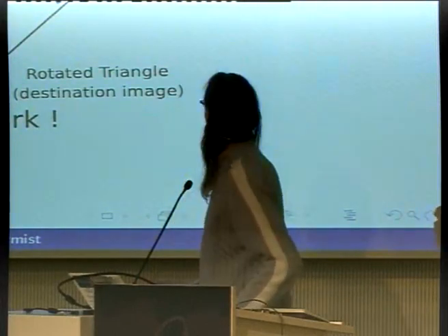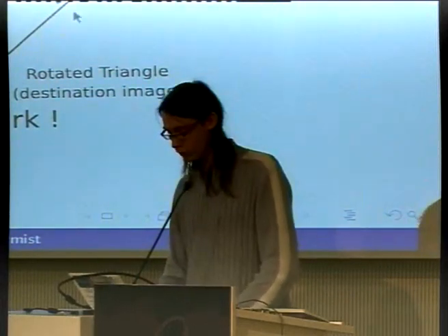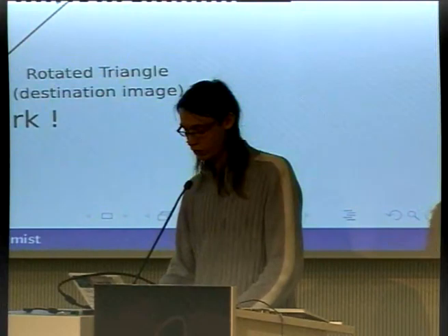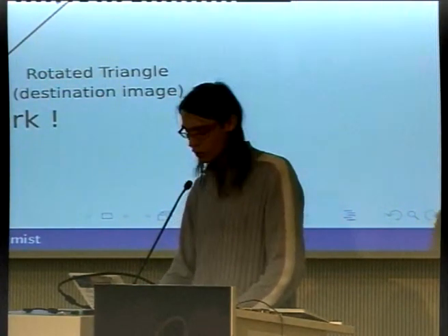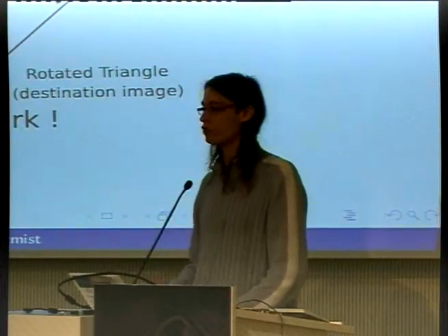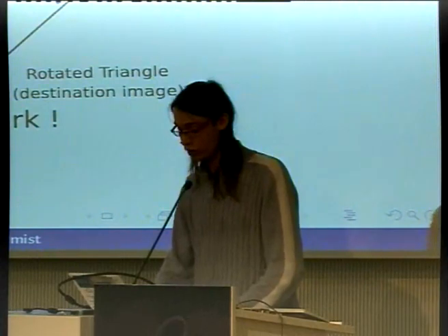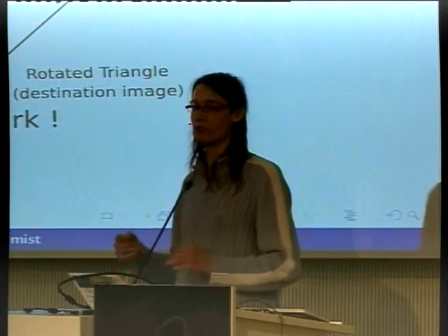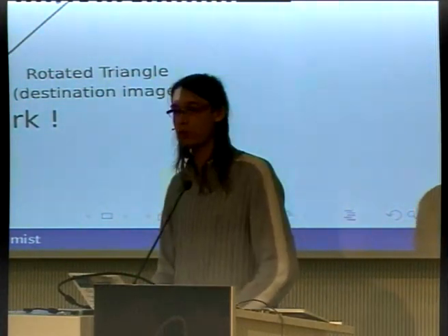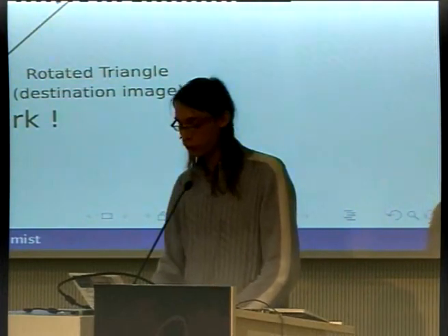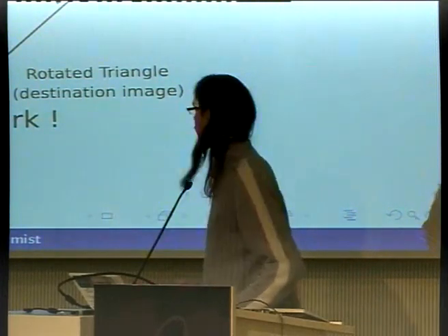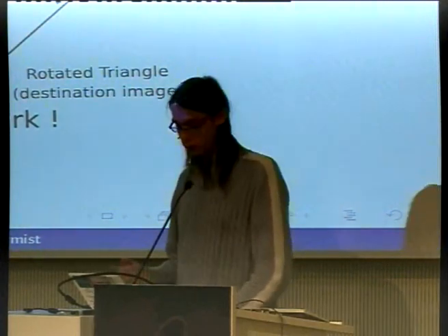And then, when the texture mapping unit draws the second scan line, it draws it like this, and these pixels need to be read, but as I said, they are now in the cache. So this will generate cache hits. These cache misses will take like 12 cycles, these pixels will take 12 cycles to be read from the memory, but these ones have been put in the cache because of the previous reads, and they will only take 1 cycle. So it looks like it can work.